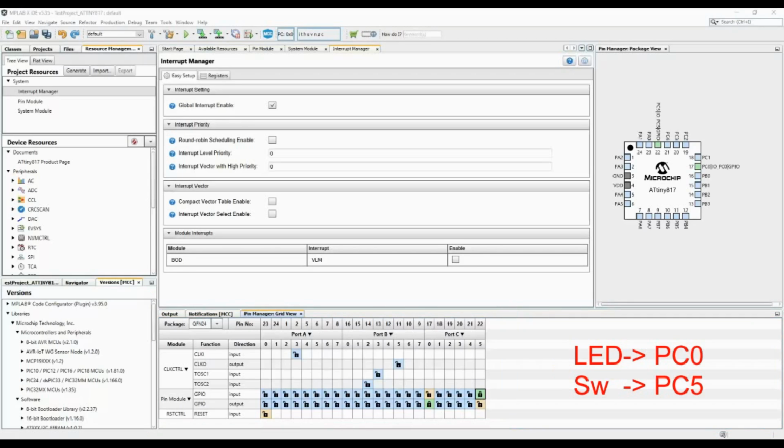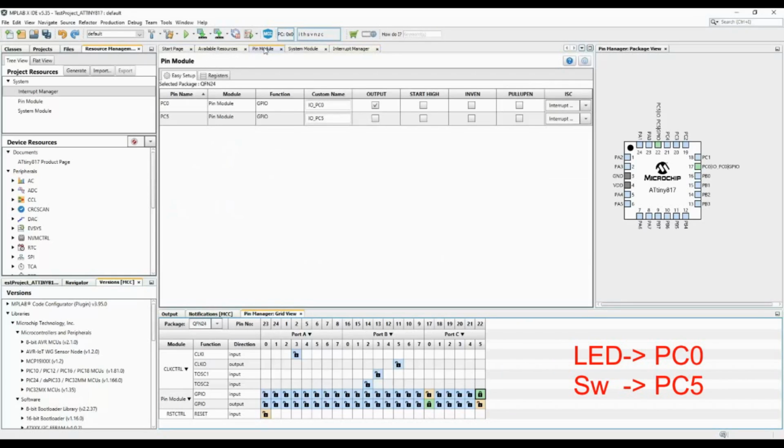After the setting, you see these two pins, the same two GPIOs we configured, now ready in the above window, and there are other related settings also for configuration, like the custom name, default output level, interrupt enable, etc.